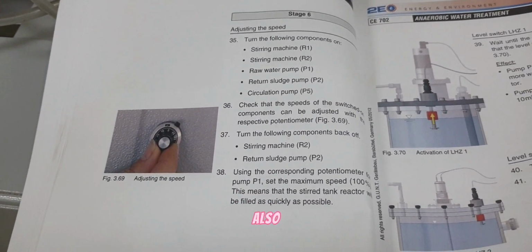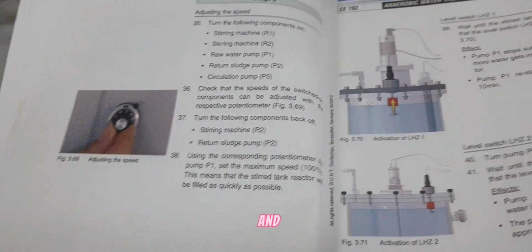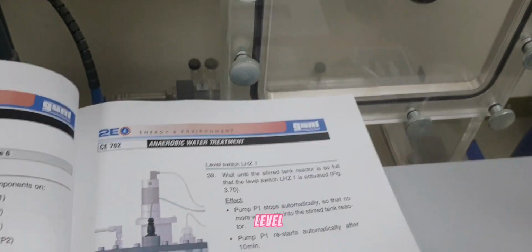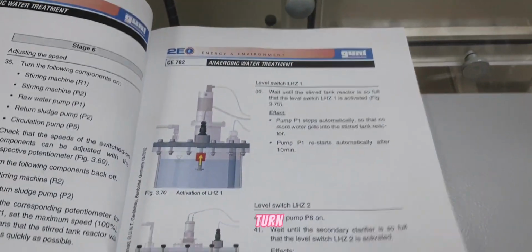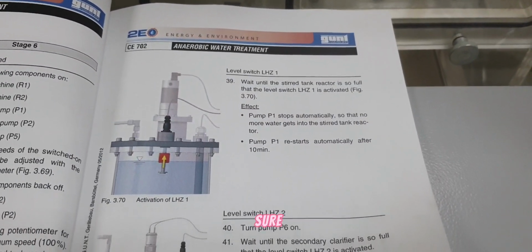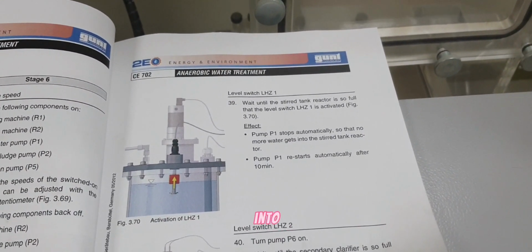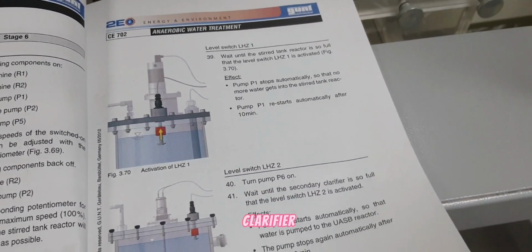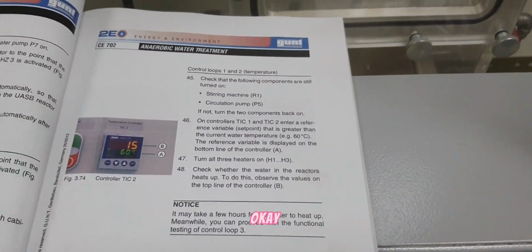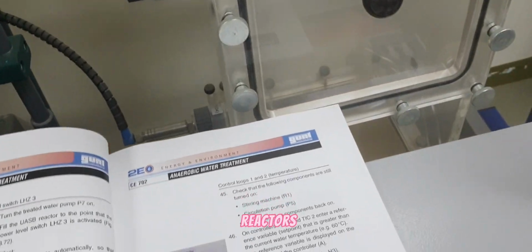Stirring machines also we have to turn on, and return sludge P2, and then we have to also check the level switches which are in the first tank, the second and third one. Also we have to make sure about the pump P1, which stops automatically, so there is no more water into the stir tank reactor. Then turn on pump 6 and wait until the second clarifier is full. Now also care about the levels in other tank reactors.